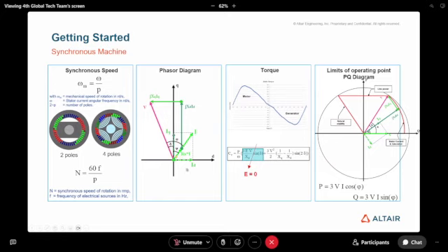There is no back EMF due to the magnet on the rotor, but there is a back EMF due to the inductance variation, through XD, LD and LQ, which is a voltage created by the reluctance variation.